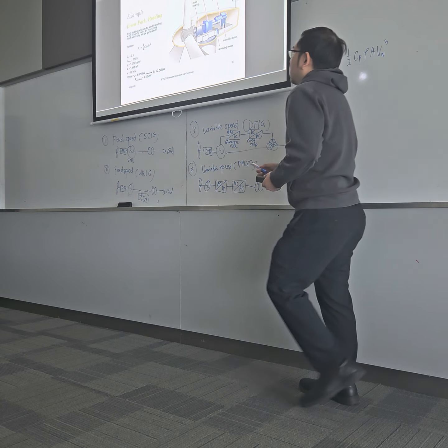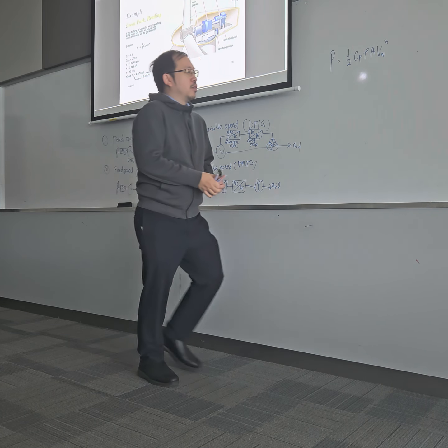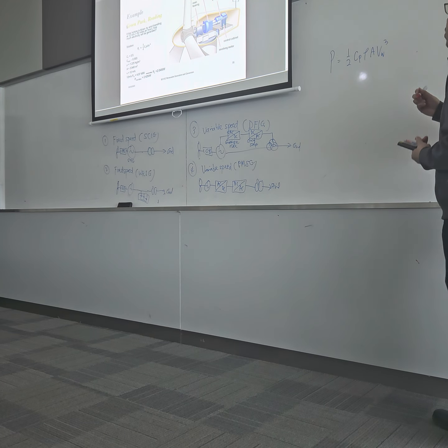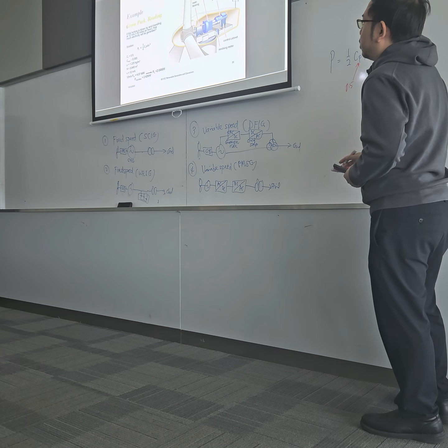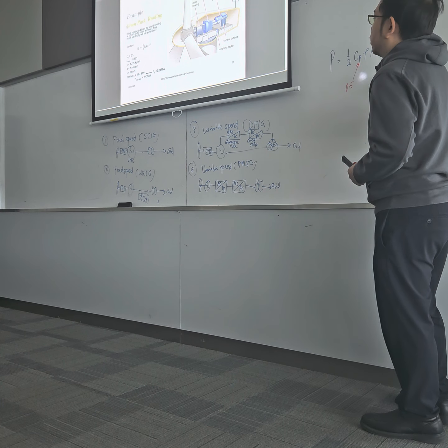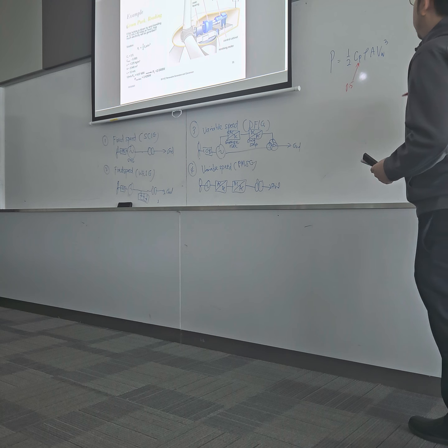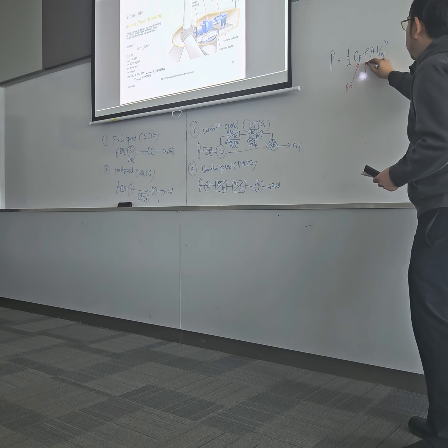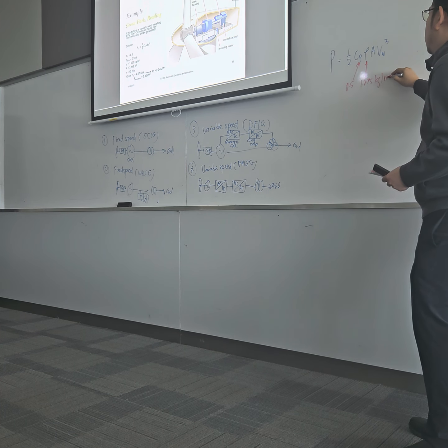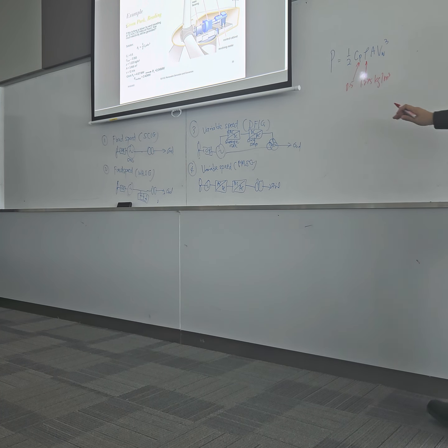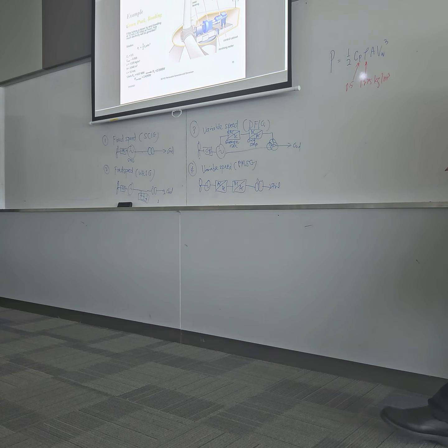We know some of these values, and some of the values we have to assume depending on the question. This question never gives Cp, so let's assume 0.5. And rho is 1.225, a constant, the density of air. Why 0.5? Because the Betz limit is 0.59, so we just assume slightly lower, 0.5.